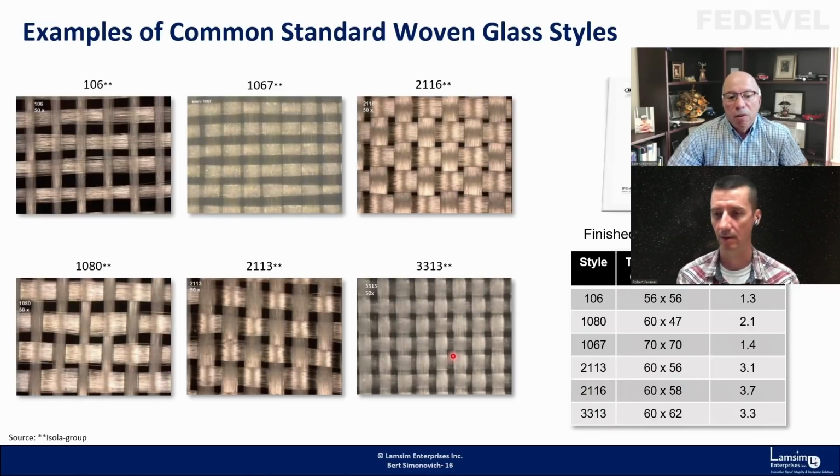Yeah, exactly. So it depends what stack up you want, and each laminate supplier has the tables. They'll say, I'll give you a 4 mil thickness, and it includes whatever number it is. So all these numbers are related to get your thickness to build your stack up. But for high speed, we're worried about skew, what they call the fiber weave effect. You can see here in 106, you have the glass bundles, but we also have these open windows, which is resin content.